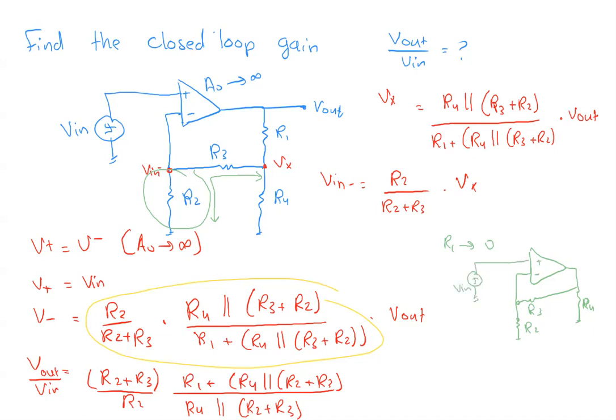And this is Vn, and this is Vout. Yeah, so basically this node is also equal to Vout. So the presence of R4 is just like a load for the amplifier. It's not in the feedback, so it's not going to be doing anything.